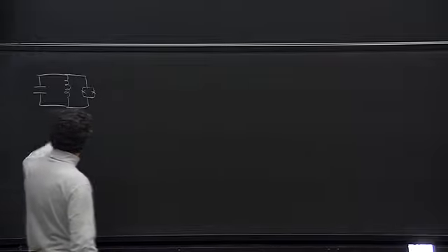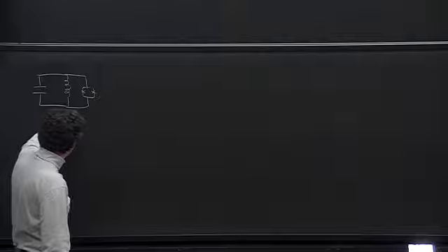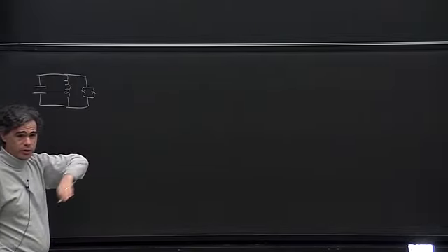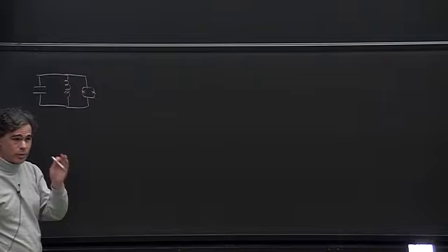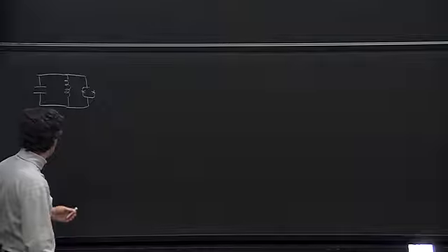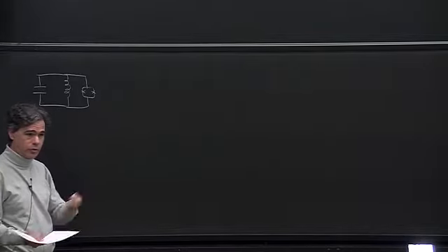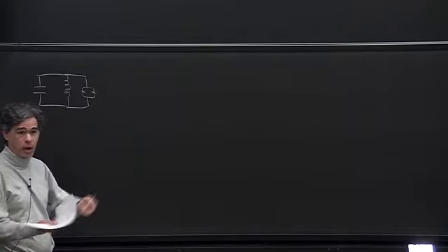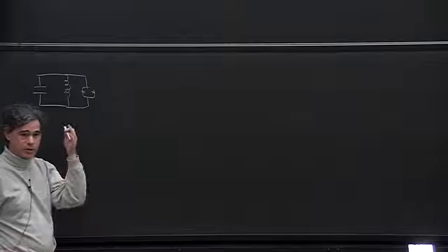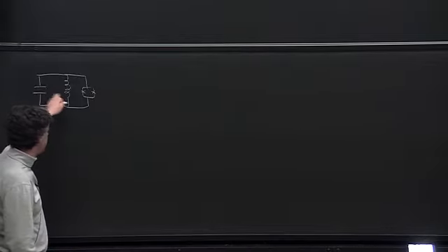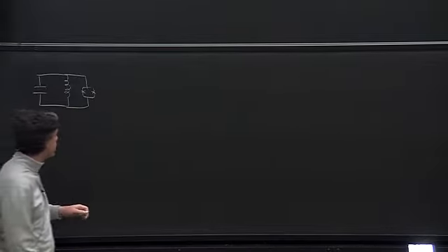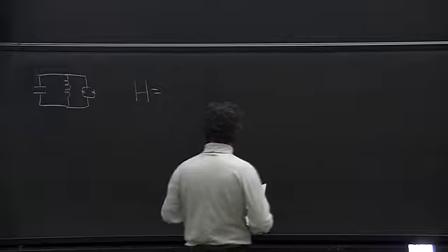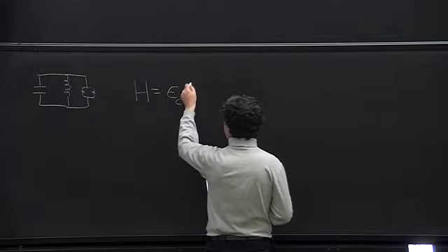OK, so if you have a circuit that's like this, or I mean, really, the real things, of course, have more capacitors and more inductors, and maybe or maybe not more Josephson junctions. But using those undergraduate circuit identities, you can combine inductors in parallel or in sequence into one like this. Okay, and so the Hamiltonian that you'll get is of this form.